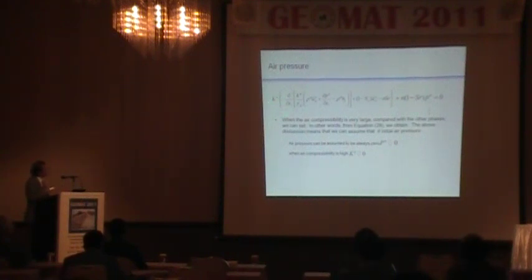We can assume that K^A, the rigidity of the air, is very low, meaning the compressibility is very high. It means K^A equals zero. In that case, we can assume that P^A, the air pressure, is zero. If we do the three-phase analysis, I observed that in the usual case the air pressure is not a large value. So in this simplified analysis, P^A is almost zero.